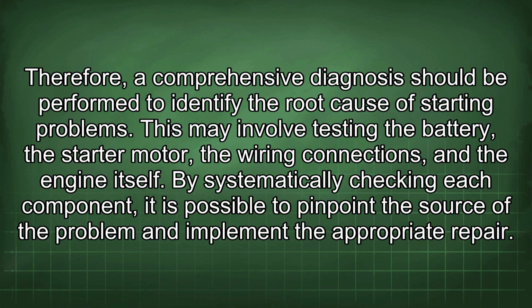Therefore, a comprehensive diagnosis should be performed to identify the root cause of starting problems. This may involve testing the battery, the starter motor, the wiring connections, and the engine itself. By systematically checking each component, it is possible to pinpoint the source of the problem and implement the appropriate repair.